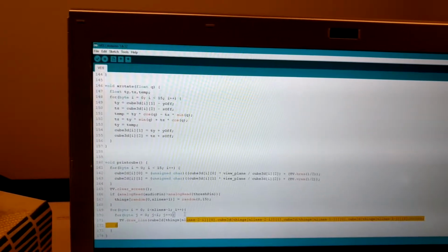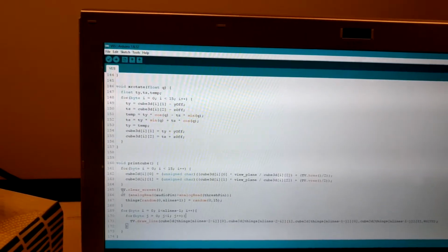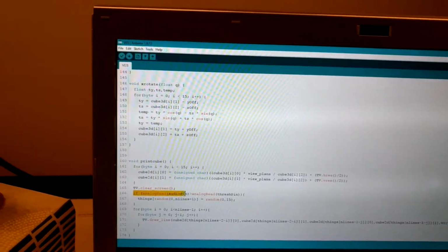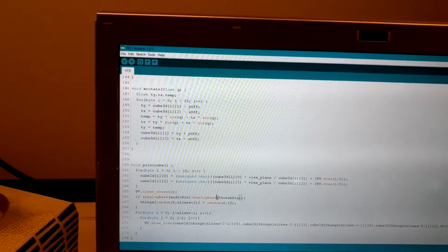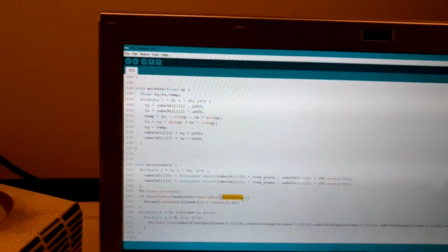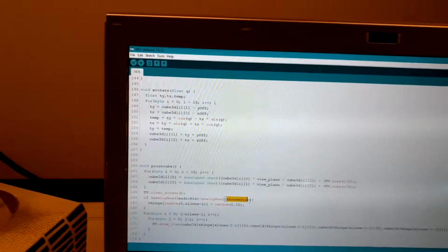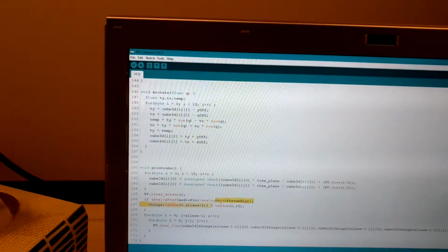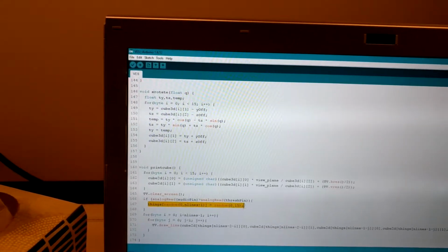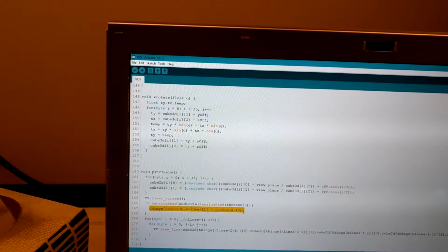And then this if statement here is the heart of the code, where I compare the reading of the audio pin from the microphone and the amplifier to the sensitivity potentiometer, and whenever it's greater, it'll select another random point and replace it in the 8 lines.